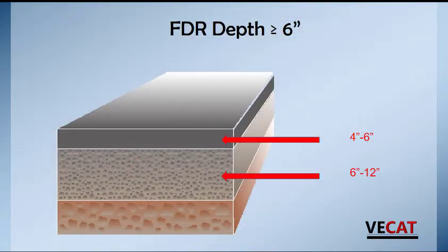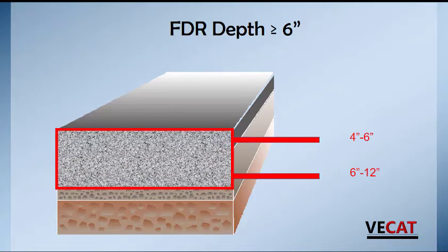Generally, in full depth reclamation, we're going to cut through the asphalt overlay and into the base material. Like I said before, we do not want to pick up the base dirt. The inherent soils underneath the materials could bring in a lot of fines and could bring in clays, moisture, and other problems. So we want to try to leave those alone and leave them out of the mix. Typically, FDR is going to go from about 8 to 12 inches deep. We're going to take that asphalt and the aggregate below it and mix them into one homogeneous layer.